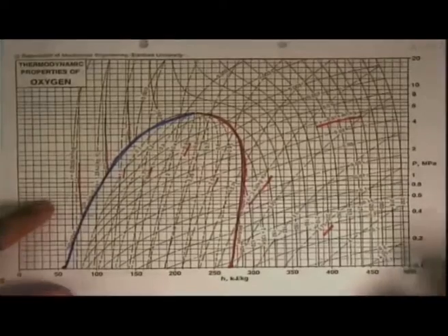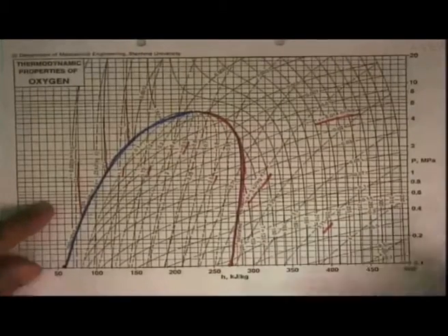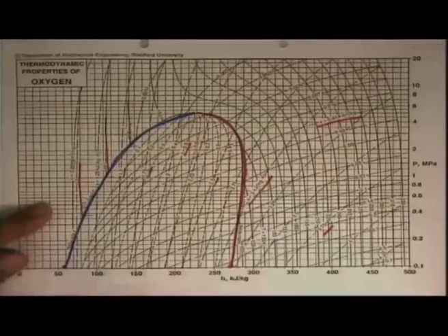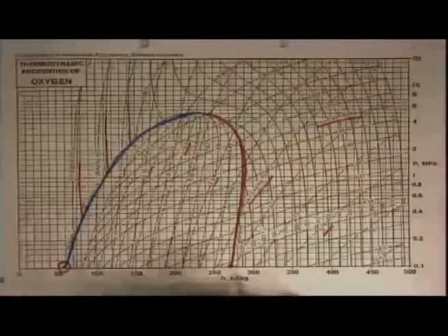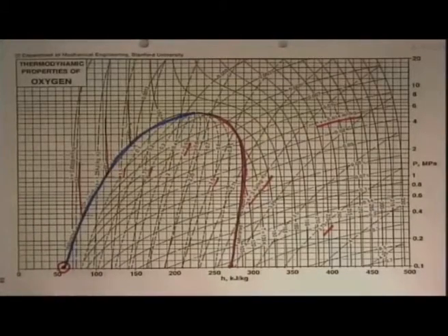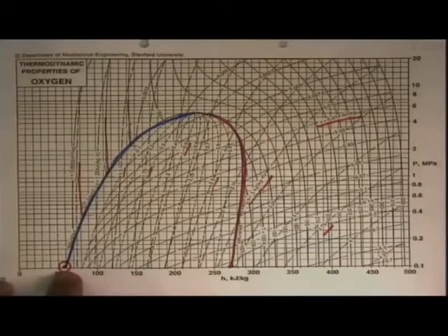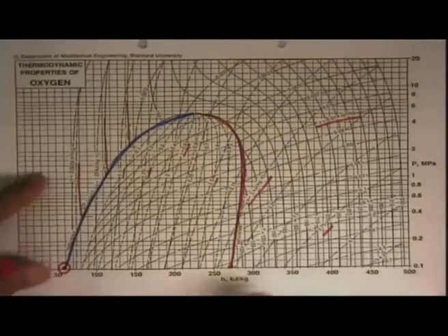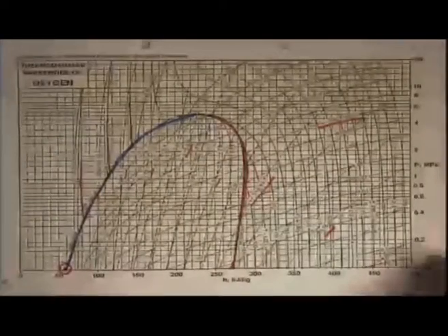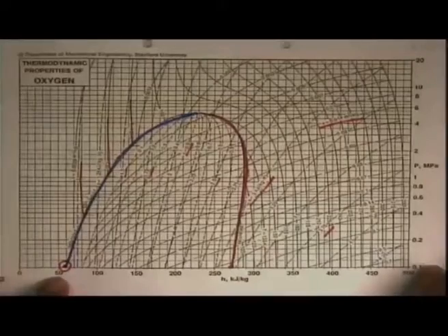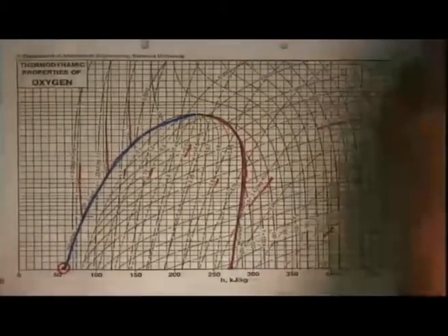And the reason for saying this is that in the cryogenic engines, picture of which I showed you yesterday, the oxidant is liquid oxygen, which is filled at this state. So we need to know what is the specific volume there, how sensitive is it to temperature, what is the specific entropy, what is the pressure and temperature to which I need to cool it, and then we know how much volume we need to have in the rocket motor to put that much liquid oxygen in it. There are many other uses of oxygen.